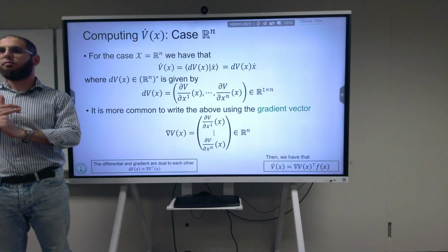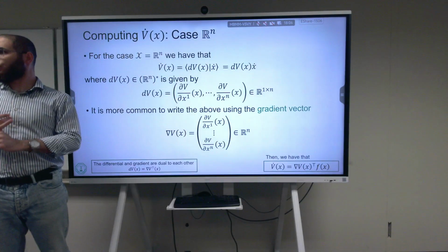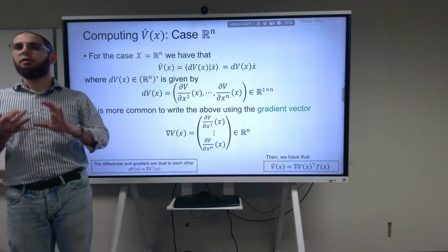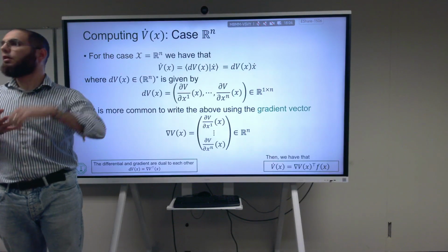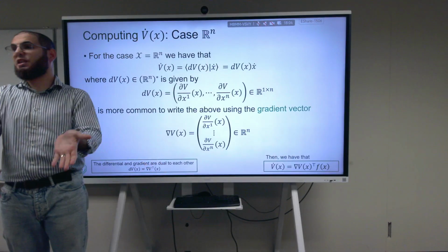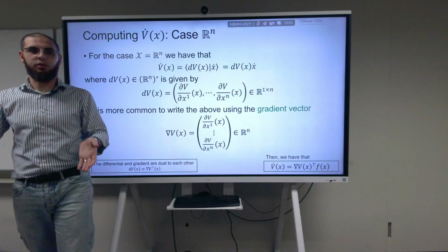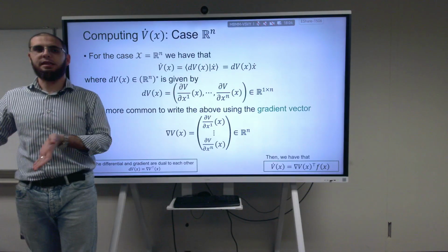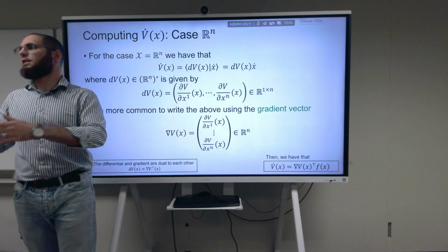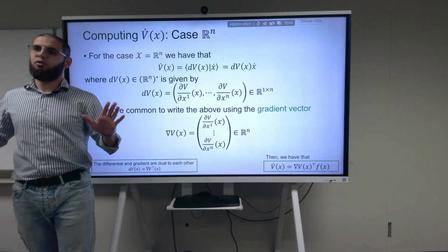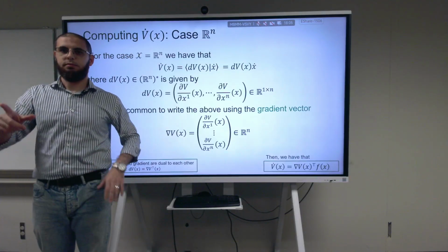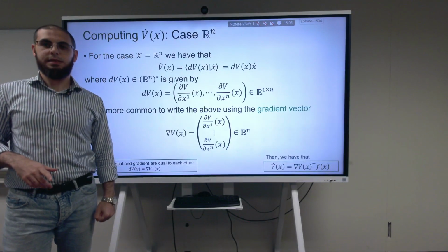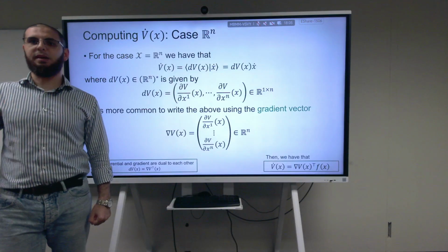So now, to implement Lyapunov's method, to try it out, choose a V. You know how to check it's positive definite. Calculate the V dot along the trajectories of the system. You have the system already, so you already have the equilibrium point that you want to check. You just check V dot is less than 0 or less than or equal to 0, and then you can conclude stability, and full stop. That's it. We had three stages of that Lyapunov: stable, asymptotically stable, globally asymptotically stable.